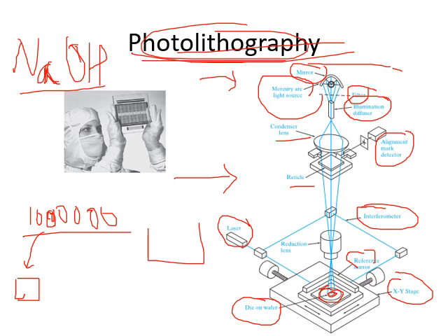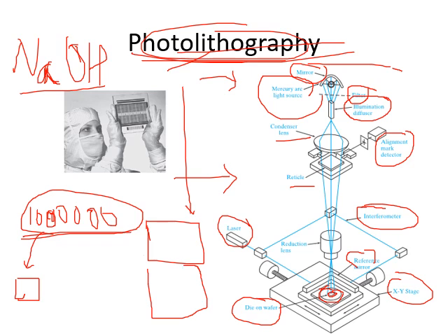See, I said we are working on the photolithography minutely. On 10 lakh transistors we are doing this photolithography, right? If there is some misalignment, if the chip has been tilted, then everything will be wasted. Why? Because the locations are being changed. So that minute realignment and refocusing is a very important part in the photolithography, correct?